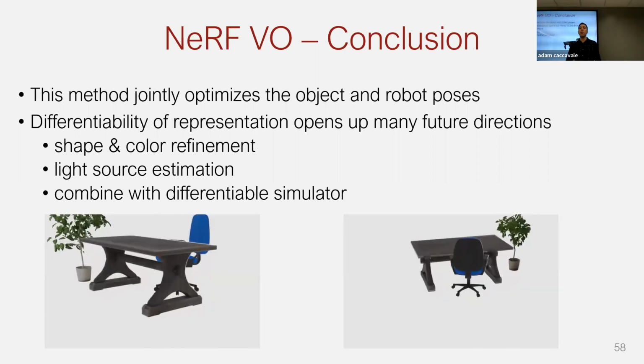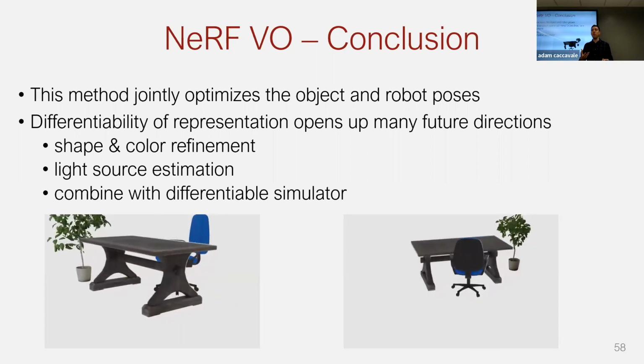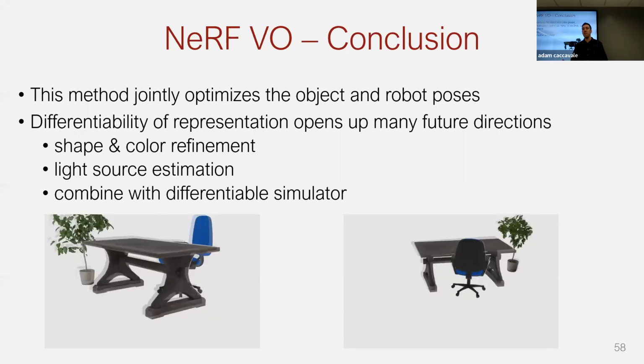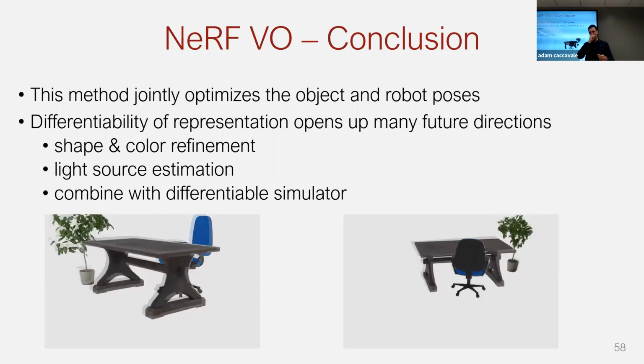Additionally, another thing you might want to estimate in order to improve the tracking would be the light source and intensity. Because we're using visual information for this optimization, and things look very different when it's in bright light or in the shadow, especially if you're running this outside, it would be really nice if you could have a NeRF that could adjust based on what you think the light source is. There is work done right now where NeRFs let you adjust this after training. And so if you could use this type of NeRF along with estimating where the light source is, you could potentially track a lot better as the object moves, say, between shadows and light.